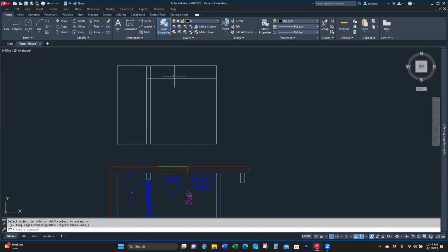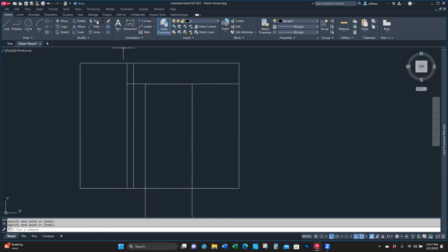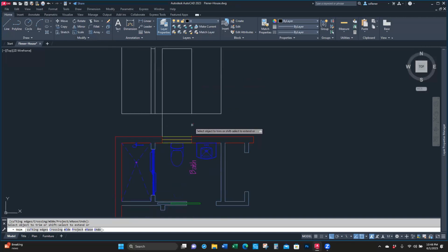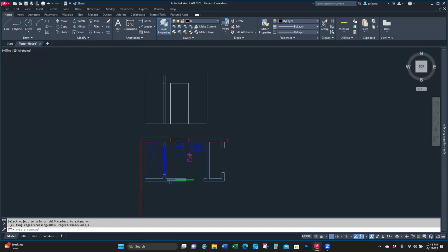And before I trim this line, I'm going to do my window. So I'm going to come up here to my window, click the edge of the window up to that 6'8" line. And then I'm going to do line on the other side of the window, click right there and hit enter. And then I'll trim between the facing and the window on the left side, and then on the right side we'll trim, and then we'll come down here and trim below the floor line. Okay.